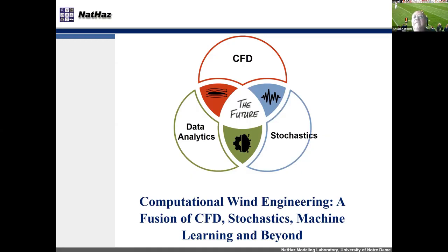So there are other techniques becoming available in CFD, which rely on data analytics or machine learning, and some part of that is stochastic emulation of what happens. One of them is multi-fidelity modeling. For example, one of my students is simulating things using RANS, which is very fast and quick, and somehow developing a bridge between large eddy simulation and the RANS, which is more quickly obtained. This type of bridge is a sort of surrogate modeling or machine learning, which helps us to develop that. And she has shown a lot of success.